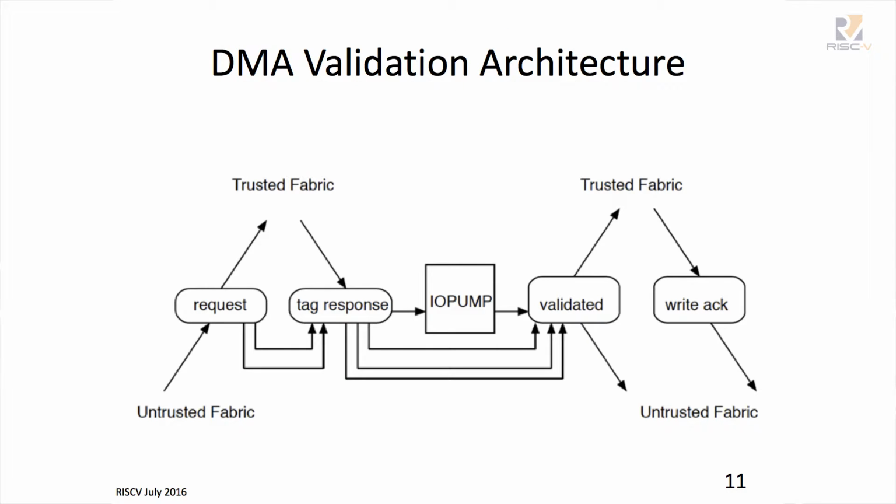Internally, we can pipeline this I/O pump so that we can run at full throughput, so that we're limited by only the throughput of the memory system and not by the latency of the round trip operation. So we can go in, fetch the tags, get them back, package that up, and feed it through the I/O pump to see if it's validated. If it's validated, then we allow a write to occur or return the read result.